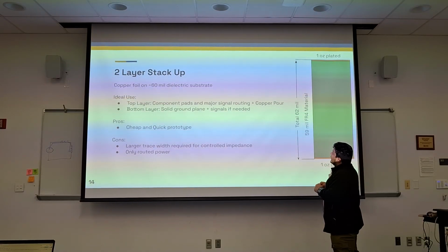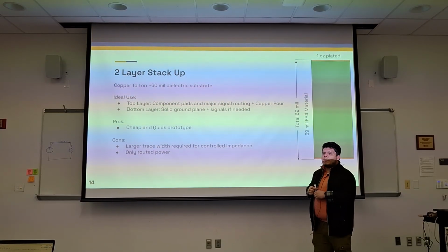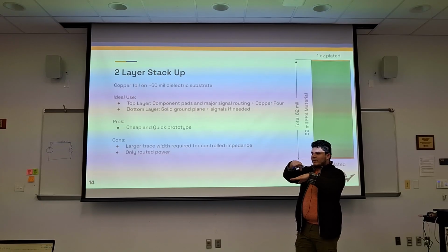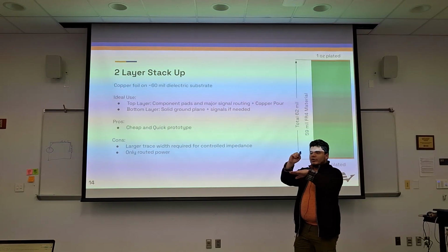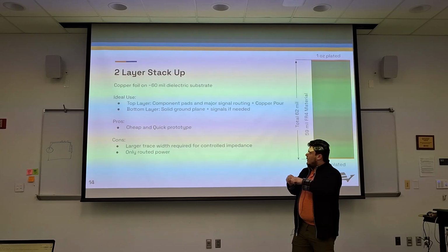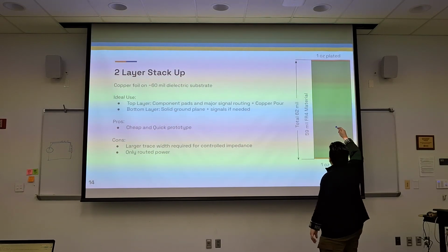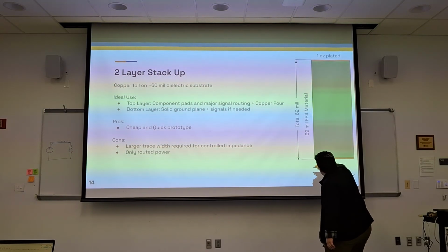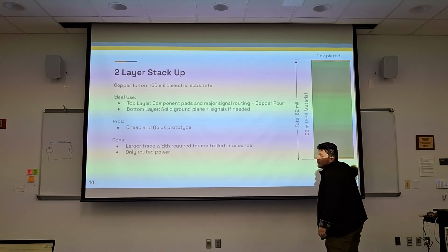Now, the problem with this two-layer stack up is we have 60 mils of a difference. So now you have a return current or a return loop that is really tall. And if we're working in fields, we have a large field going around the entire board, right? You can think of our electromagnetic field going across all 62 mils.